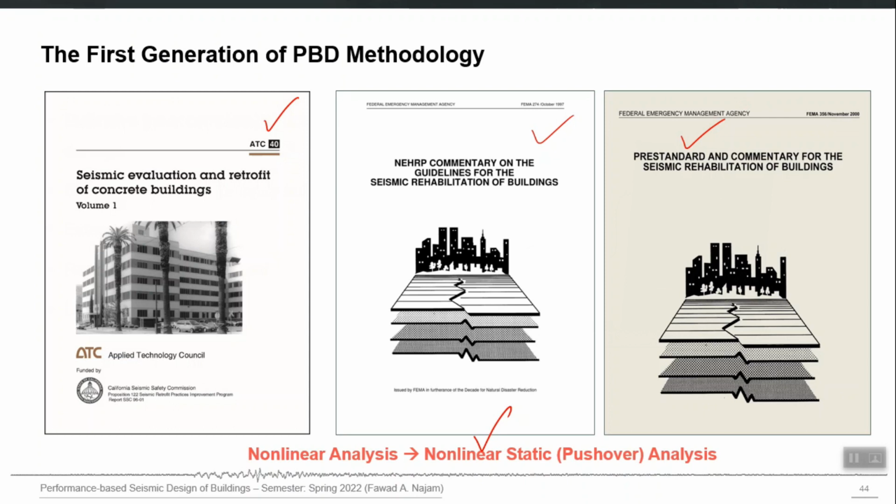But now the next generation of PBD, the current state of the art guidelines, they recommend nonlinear dynamic analysis, nonlinear time history analysis. So you are already familiar with time history analysis, direct integration or modal RHA, but for nonlinear it will be only direct integration. So the computer model used for that analysis will be nonlinear, and will be able to simulate all the damages, right?